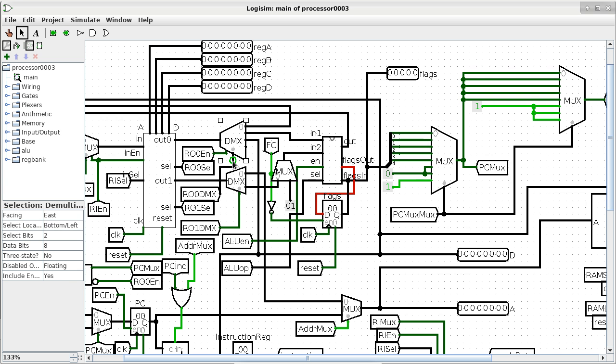So obviously there's a connection between the number of lines going out and the width of the control line. In this case, what do you think is going to be the bit width of this control line? We got 4 outputs, so we have to be able to select one of the 4 outputs. How many bits do I need to use to select 1 out of 4? 2, very good. So it is in fact a 2-bit wide control line, because 0,0 would select the first line, 0,1 would select the second line, 1,0 would select the third line, and 1,1 would select the last or the fourth line. Is that okay? Does that explain what that line is? Okay, good.